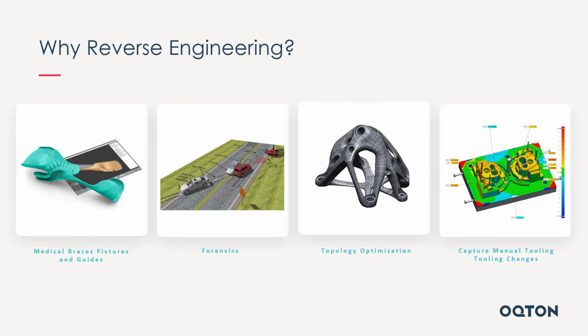And the last one here is one that I discovered by visiting some manufacturing. There was a manufacturer that did some stamping, and they'll do a design for a stamp, and then they manufacture that expensive tool, and then they roll it out, and they start stamping out test parts, and then they dimension them. They do their first article inspection. When they do that, they discover that, oh, if I add a little material here or I round off this fillet edge just a little bit here, it'll help create a better part.